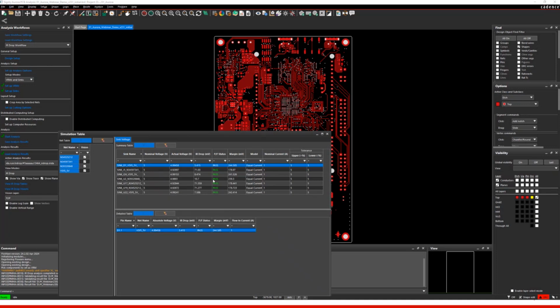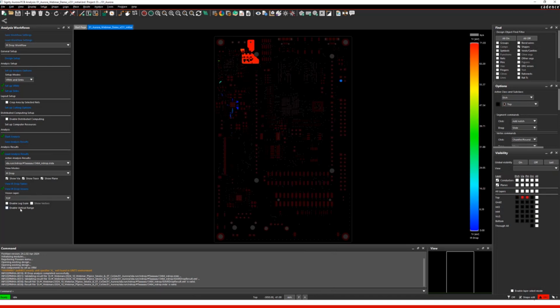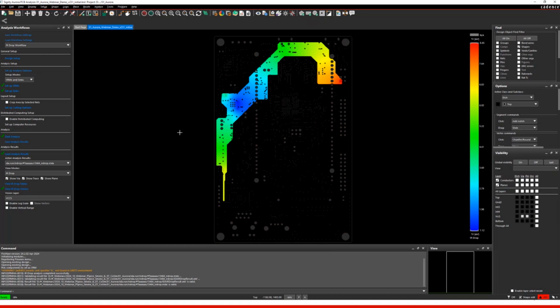You can choose the pass/fail, that means how much voltage is dropped due to your losses. But I think more or less it's interesting to see the visualizations. And then we select here VCC5, for example. Then we can see how that would look like. And here in this case, 8 millivolts is not very critical, because it is also a very simple structure.